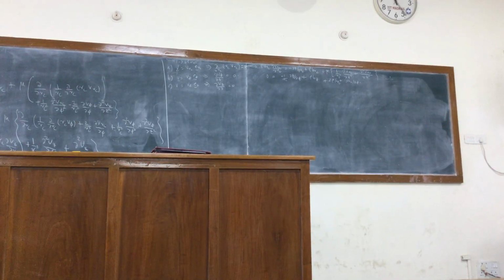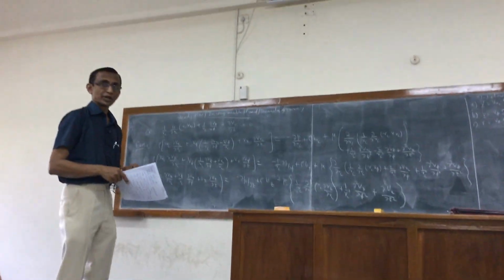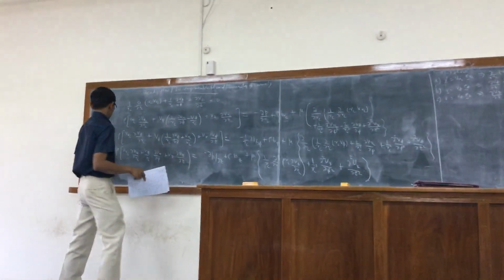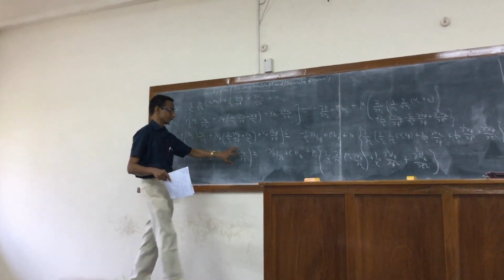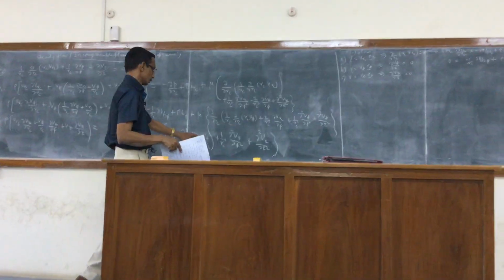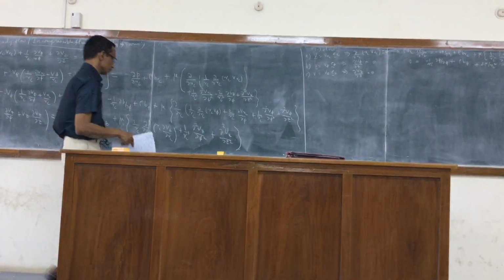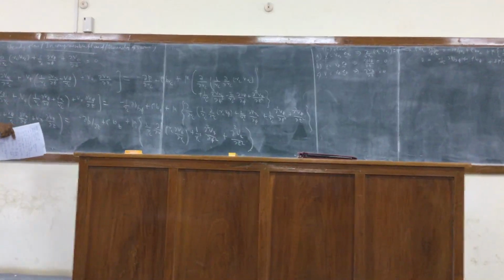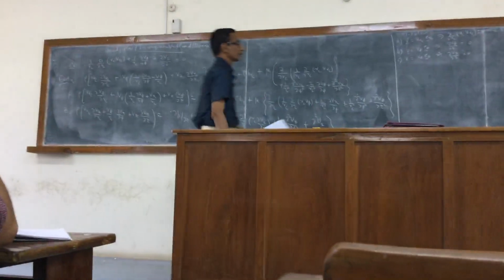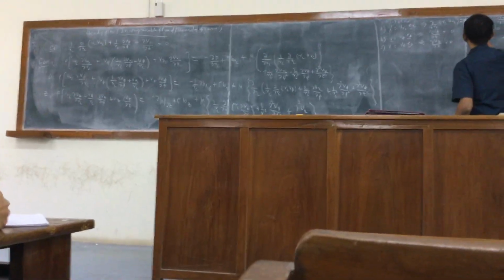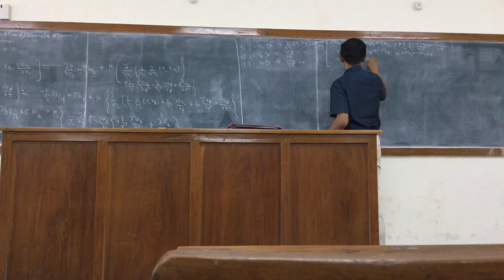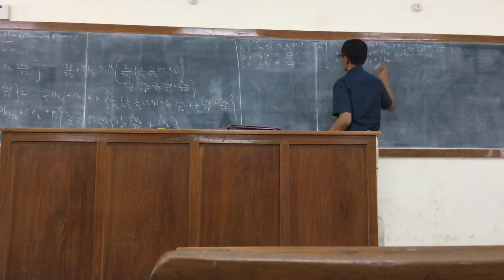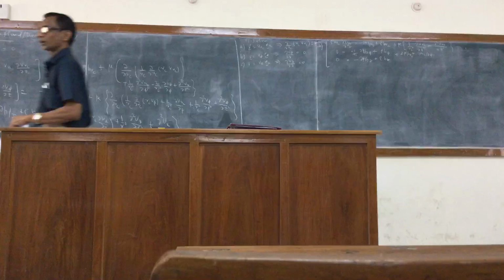Right? So this is what the equation of motion tells me. Probably based on the physical situation, you can make further approximations and simplifications. Right? So then if you go to the third equation, d by dz is 0. This is entirely 0, and you will see that all other terms are 0, and so we simply get 0 equal to minus dp by dz. So this is all for case A. I'm not expecting you to remember all this, but if you're going to solve the problems, it might be worthwhile writing it down.